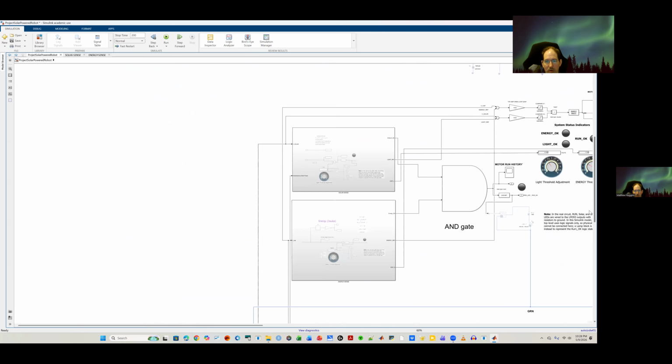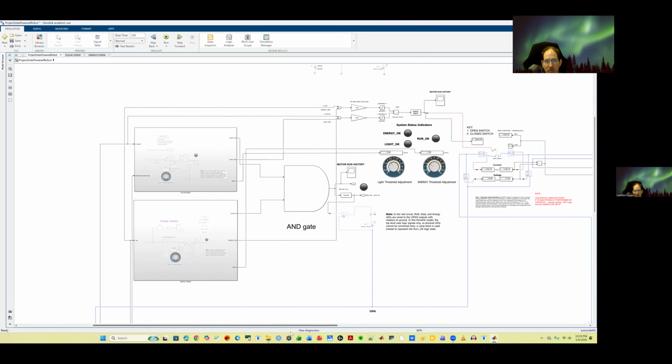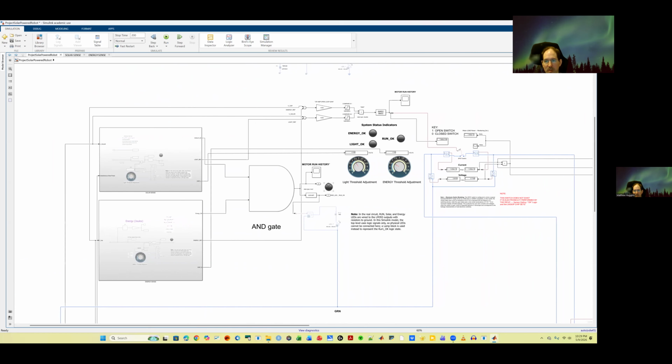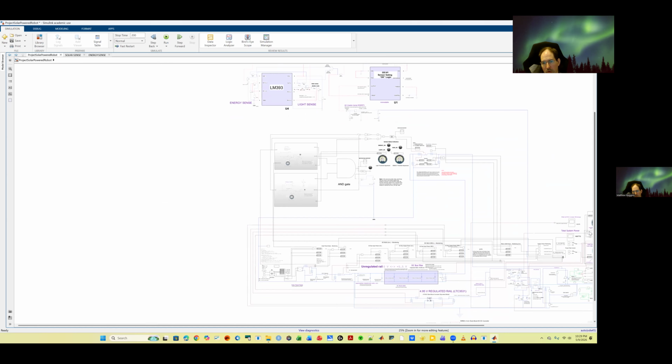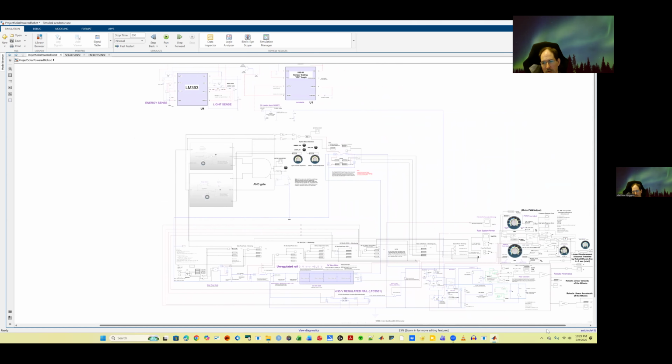And then I modeled the comparators using both Simulink and Simscape Electrical. That's why I have it repeated twice, because some parts of the system would only accept one version or the other. So behind here, I'm using one version, and through here, I'm using a Boolean. One is using Boolean logic, and one is using voltage levels. One would only accept voltage levels, and the other would only accept true and false statements. So I end up using both. And that concludes the overview of the entire circuit, which is pretty quick.